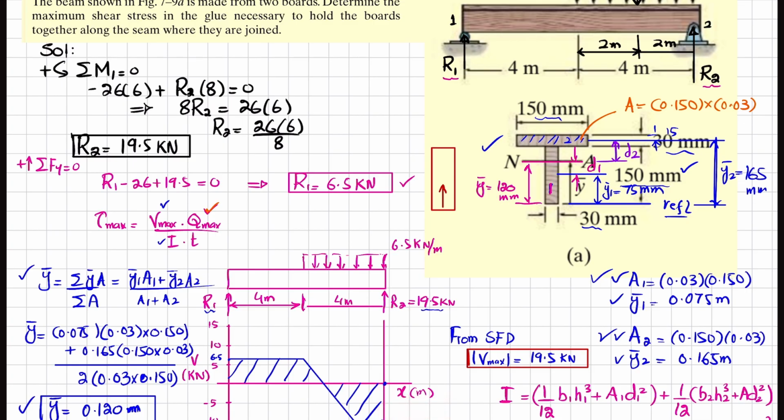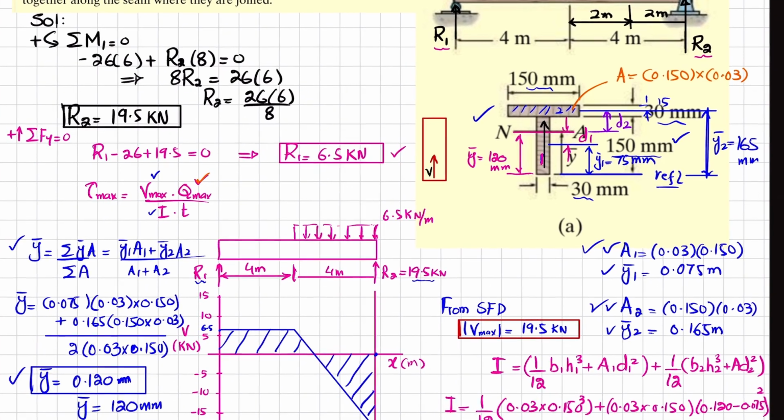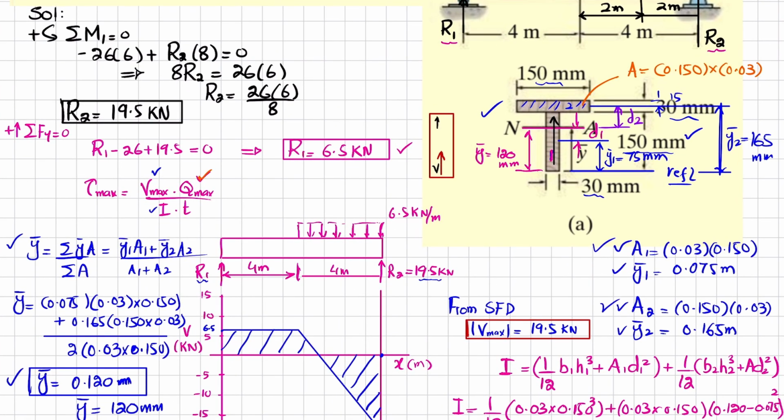So if I represent the shear force on this element as vertical, this will be V, and the representation of stress will be like this. So this shear stress will be 4.88 megapascal, and that will be tau. Now if I represent it on a three-dimensional element, this representation will be exactly like this, where these shear forces are upward.